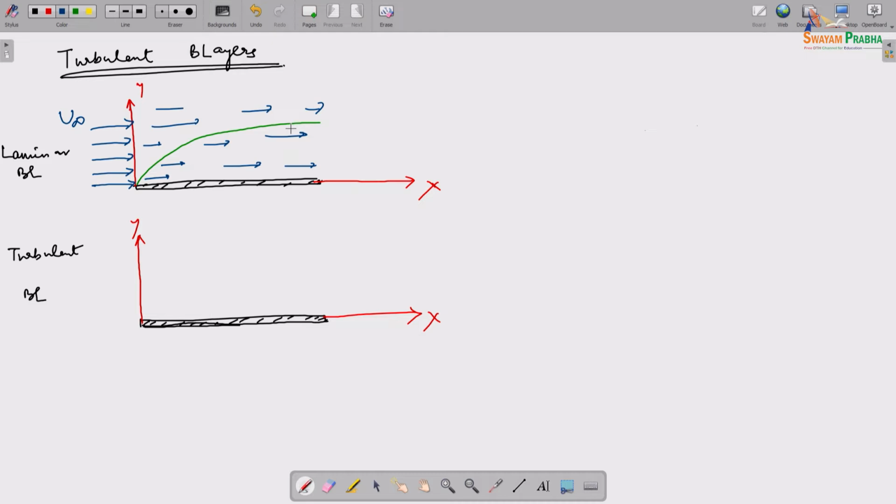But what is different? You had the free stream which came in here, but then there was no flat plate. Now it's encountering the flat plate. I've drawn this green thing, but this is the demarcation of the boundary layer flow, which is here, and this is dominated by viscosity, and a little distance away from it, it's again just a free stream where the effects of viscosity are negligible, minimal. So, we can ignore that, we use potential flow to solve that.